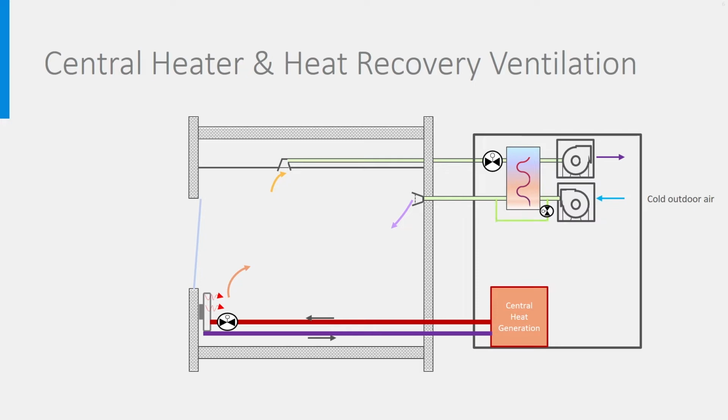If it is hot, the air does not need to be preheated because it is already warm, outdoor and indoor. Then it can bypass the heat recovery heat exchanger.